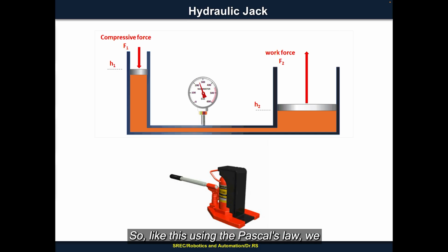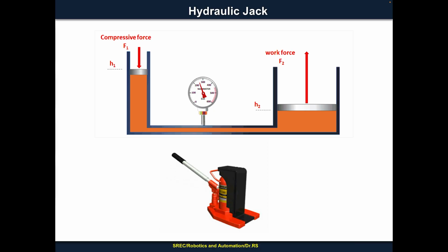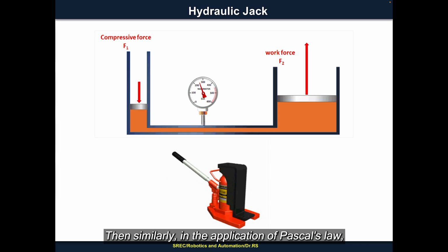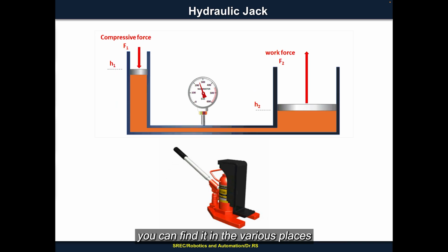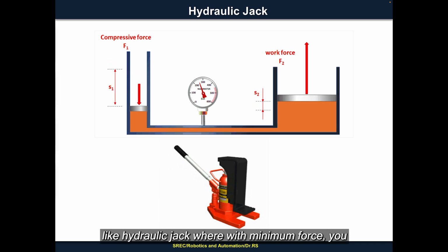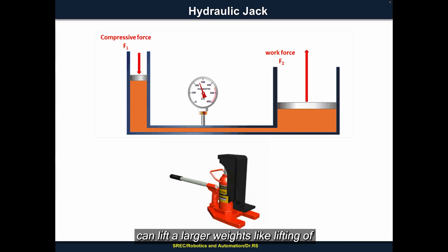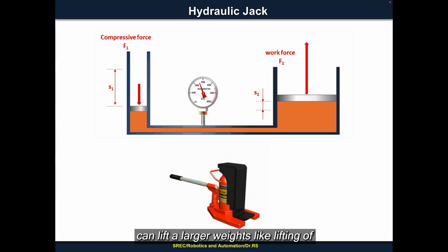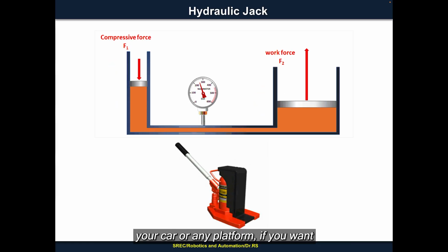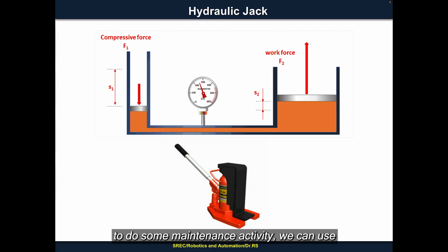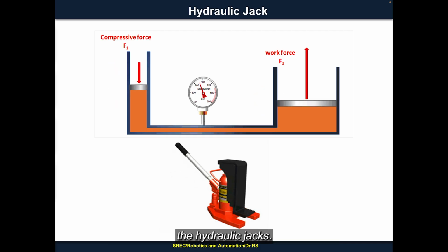So like this, using Pascal's law, we can estimate the force values or area or even the pressure values required for the particular application. Then similarly, you can find the application of Pascal's law in various places like the hydraulic jack, where with minimum force you can lift larger weights, like lifting of a car or any platform. If you want to do some maintenance activity, we can use the hydraulic jacks.